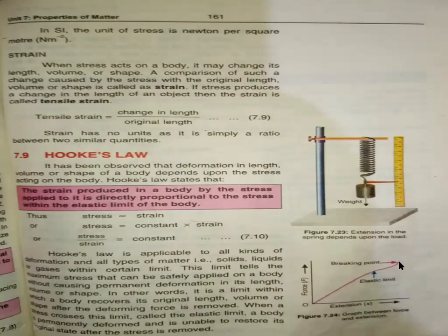But after this point, if I apply more force, what will happen? Either the shape or the volume of the body will change and the body will not come to its original position. If I keep on applying more and more force, you might have seen the body will break and never come back to its original position. So this is the elastic limit. After this, Hooke's law is not applicable. Hooke's law is applicable from this point to this point, only up to the elastic limit.